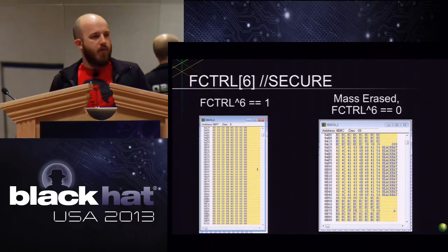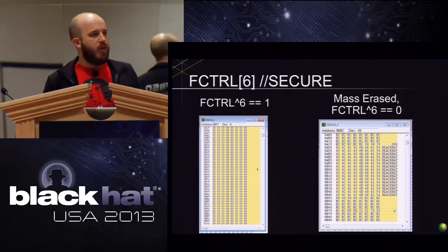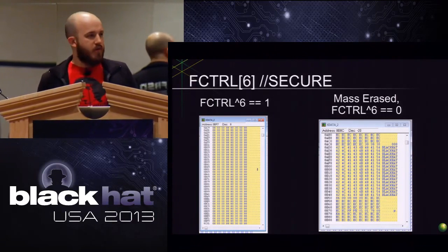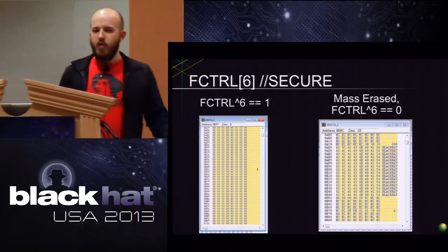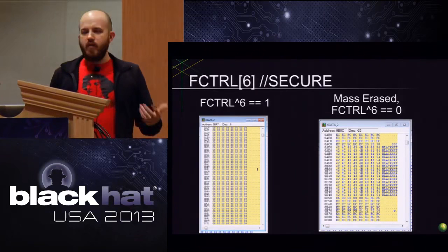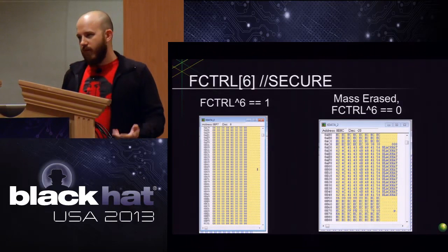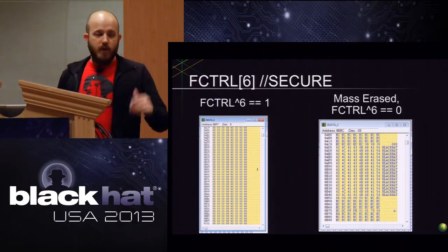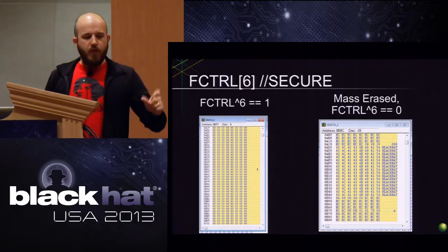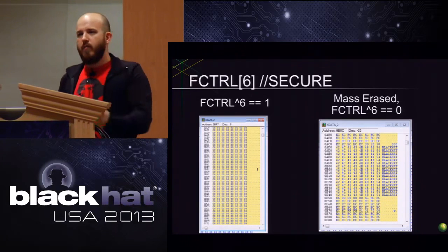Now, that may or may not matter depending on the particular use case. This is like being able to see RAM without being able to see the code, so you don't necessarily have any context to know what these things are, outside of knowing what the device does. Let's say it's a smart meter doing encryption as part of an ANSI standard. You know certain things about how that's going to work: what type of encryption it uses, what its key sizes are. And the way that's implemented in code will most commonly require you to copy that key out of code memory into RAM to then perform operations on it.